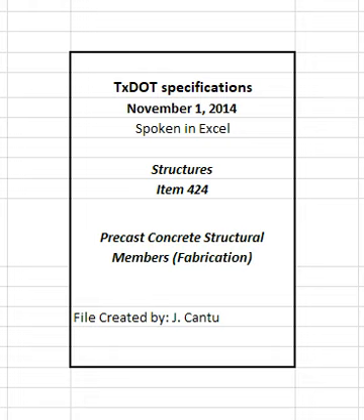4.2.1 Forms. Design forms to prevent damage to the concrete from restraint as the concrete shrinks, from form expansion and contraction from thermal changes, from stripping operations, and from dimensional changes due to pre-tensioning. Forms, regardless of material, must conform to the profiles, dimensions, and tolerances of the finished product as specified on the plans and in this item. Maintain forms free from dents, grease, or other foreign materials that may affect the appearance of the member, and clean forms thoroughly before each casting operation and immediately before applying a form release agent.